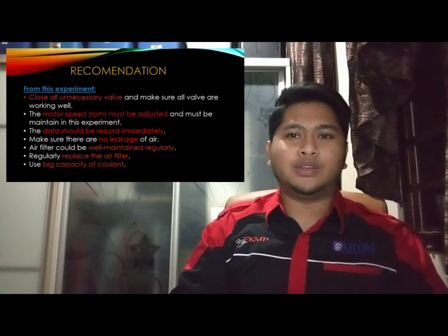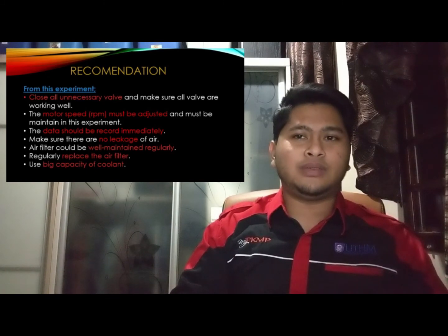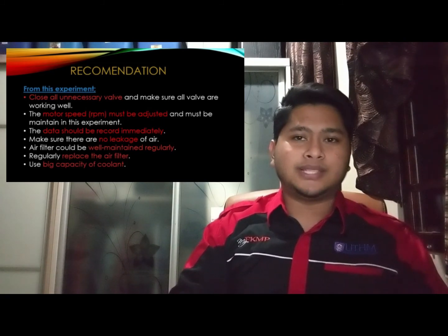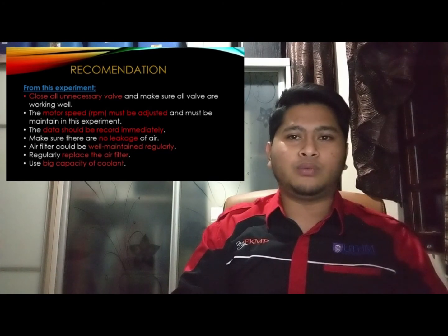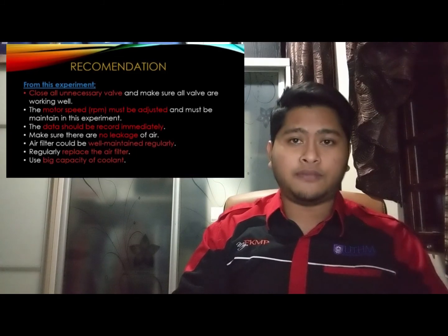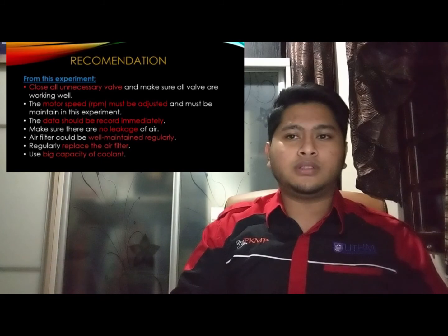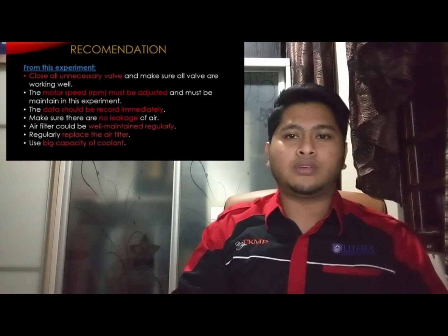Moreover, make sure there is no leakage of air to prevent pressure drop, which may lead to lack of capacity and cause the data to be inaccurate. Besides, the air filter should be well maintained regularly to prevent unwanted pressure caused by clogs at the air filter. Also, we should regularly replace the air filter so that it will not affect the capacity of air to the compressor.